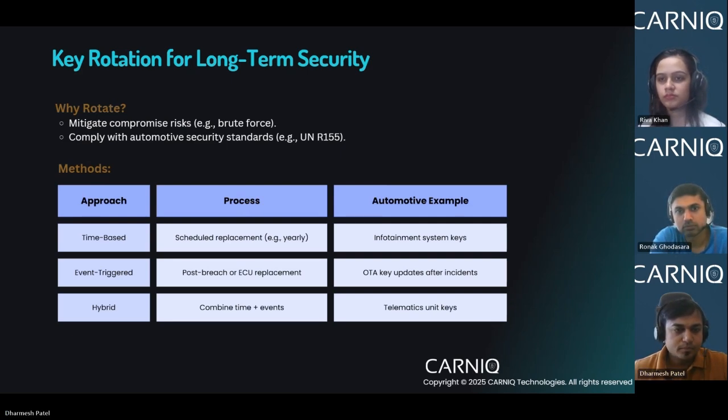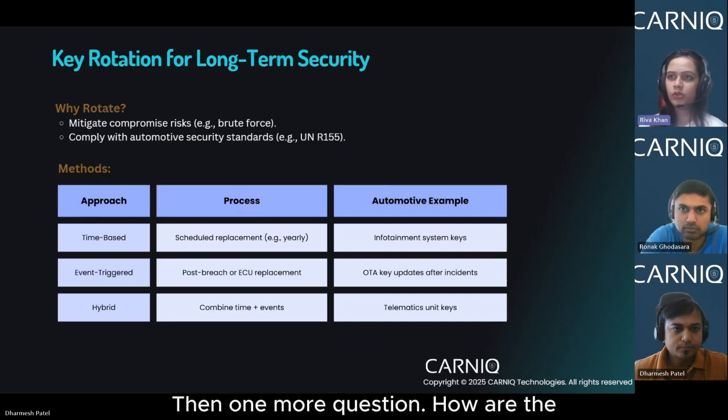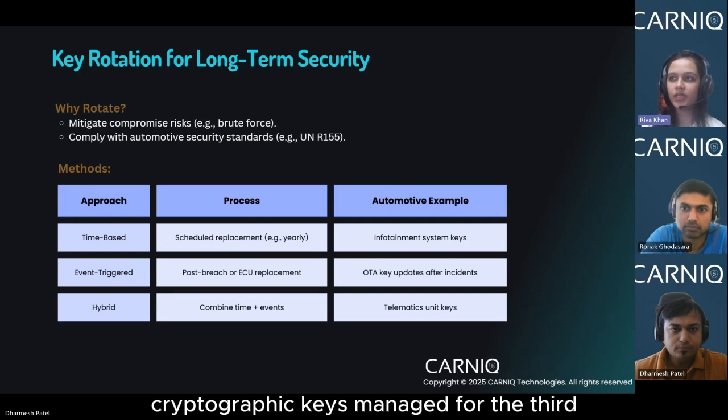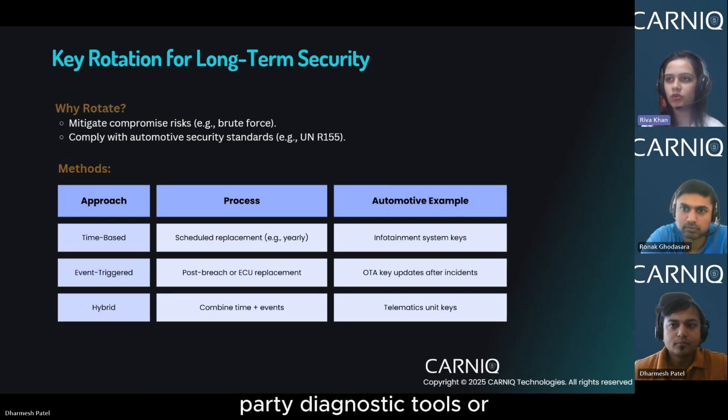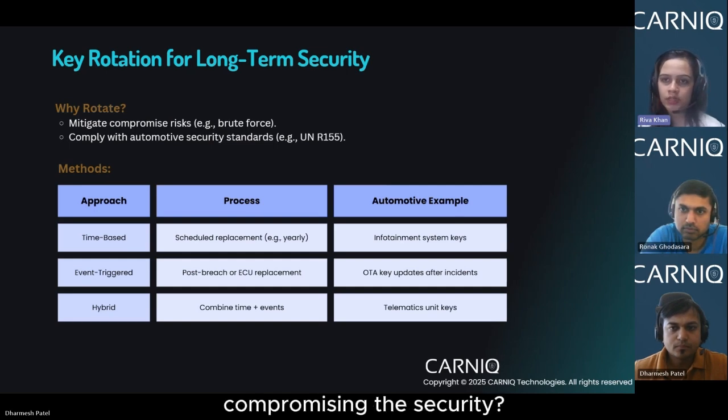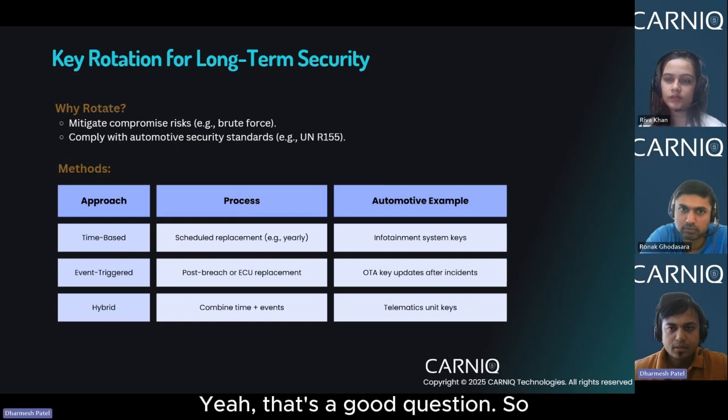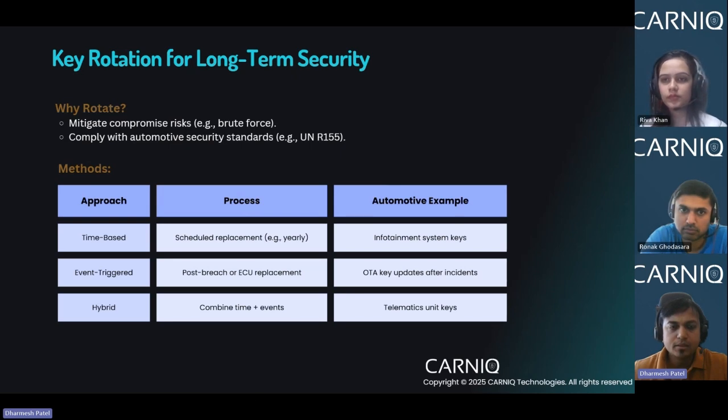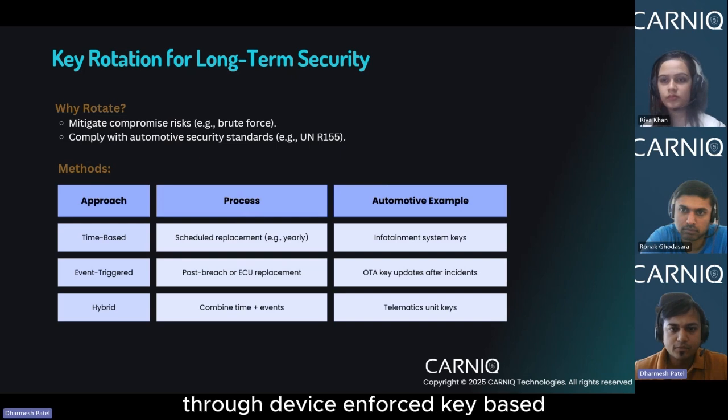One more question. How are the cryptographic keys managed for third-party diagnostic tools or aftermarket ECUs without compromising the security? Yeah, that's a good question. To answer your question, it's OEM-controlled access, so time-limited certificates are issued to authorized repair shops, and the J2534 pass-through device enforces key-based authentication.